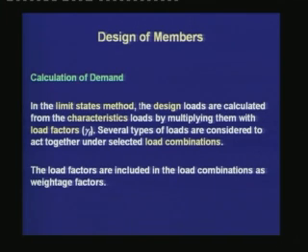In the limit states method, the design loads are calculated from the characteristic loads by multiplying them with load factors which are represented as gamma f. Several types of loads are considered to act together under selected load combinations.